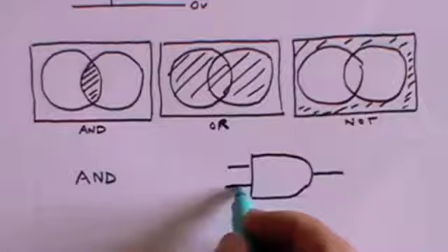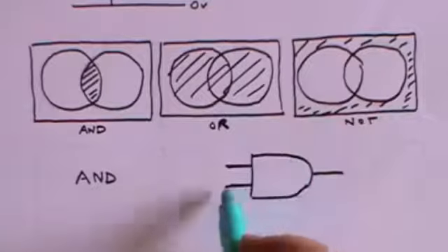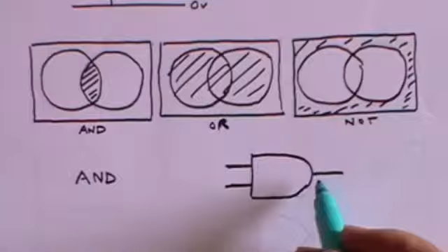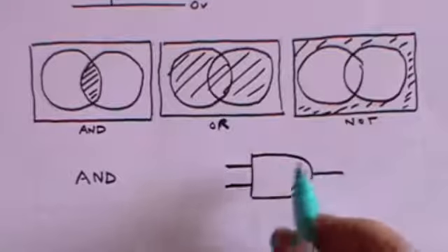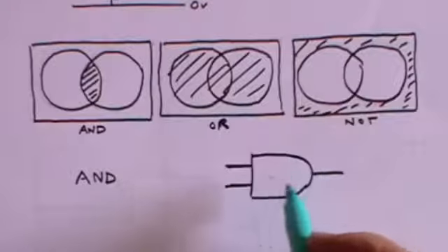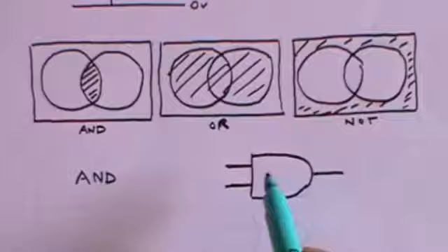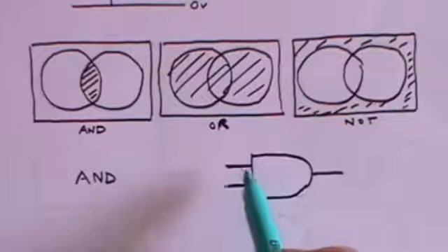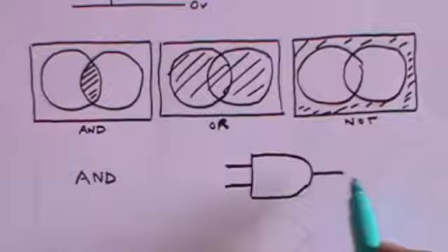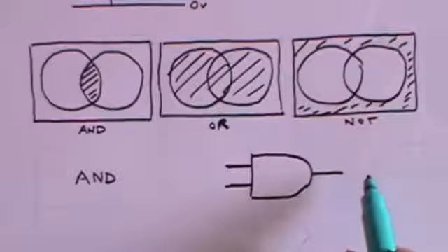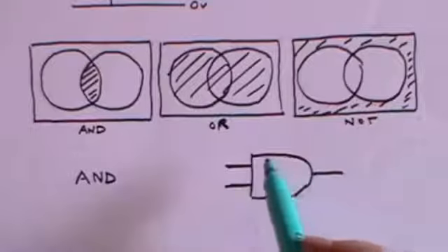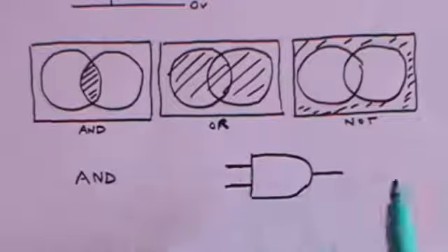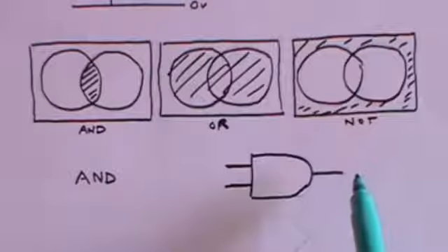And what it means is that you've got 2 wires coming into a device. We'll actually design the device in a little while. And 1 output from the device. In here there's some electronics, which I haven't told you about. But the idea is that if both inputs have positive voltages, then there will be a positive voltage out. But if either one or both have no voltage, then there will be no voltage out.